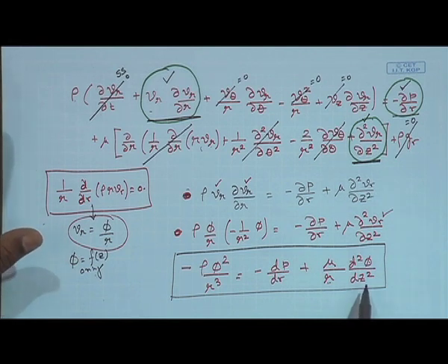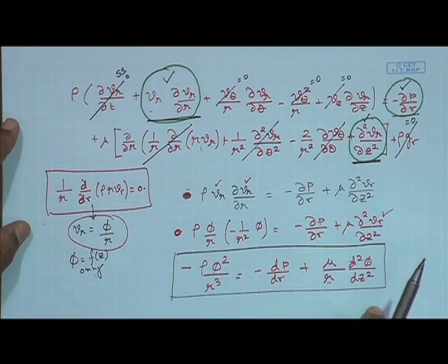So again you see the utility of the Navier-Stokes equation, how easy it is to at least arrive at the governing equation. There is no need to think of any complicated shell, which would be very, very complicated in this case. You simply pick the direction in which the velocity varies and try to solve it. So this is your governing equation.